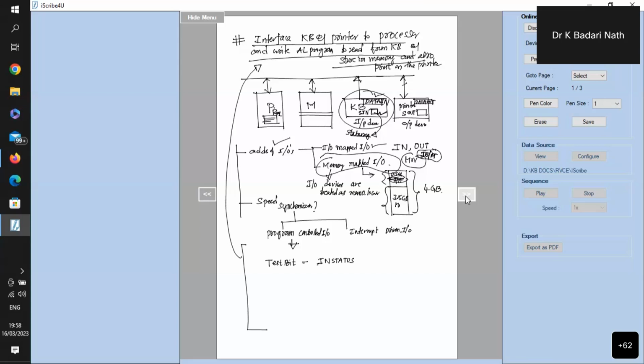Now which bit am I testing? Bit number 3 I am testing. So this instruction always affects the result. Test bit is nothing but an AND instruction. So whenever bit 3 is 1, the total answer becomes non-zero. By chance, if bit 3 is 0, the total answer becomes 0. That means this instruction will set what is called the zero flag.